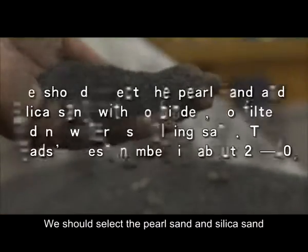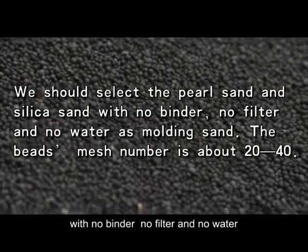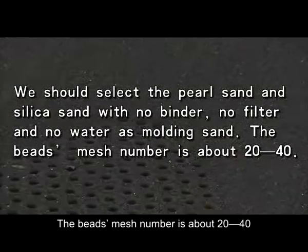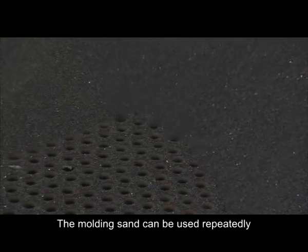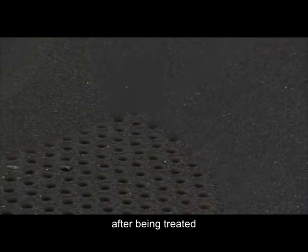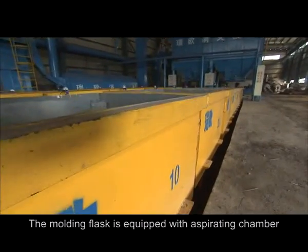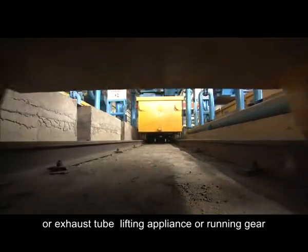We should select the pearl sand and silica sand with no binder, no filler and no water as molding sand. The mesh number is about 20 to 40. The molding sand can be used repeatedly after being treated. The molding flask is equipped with an aspirating chamber or exhaust tube, lifting appliance or running gear.